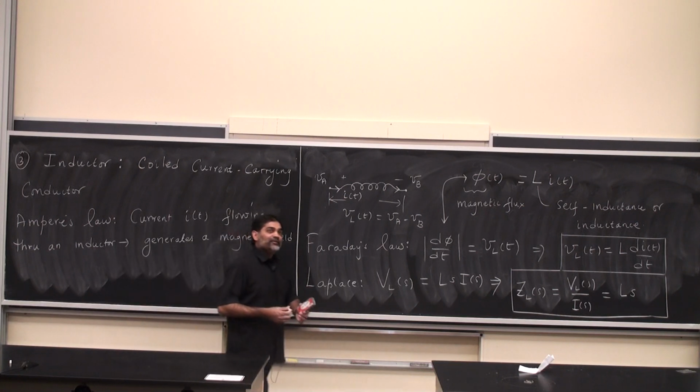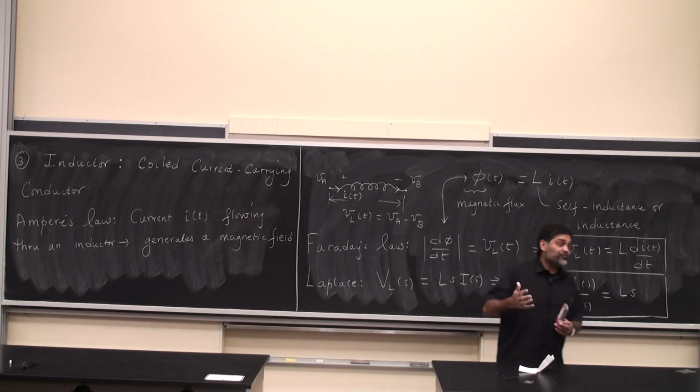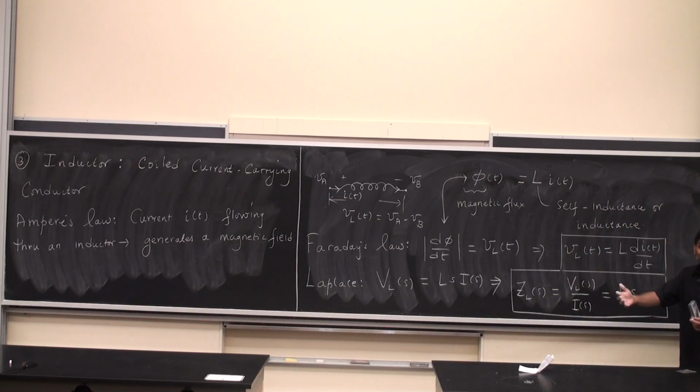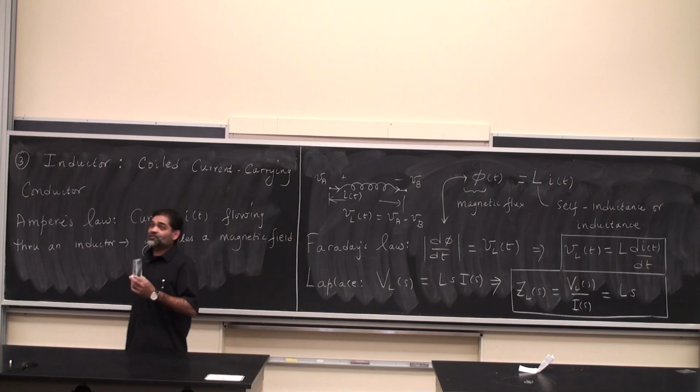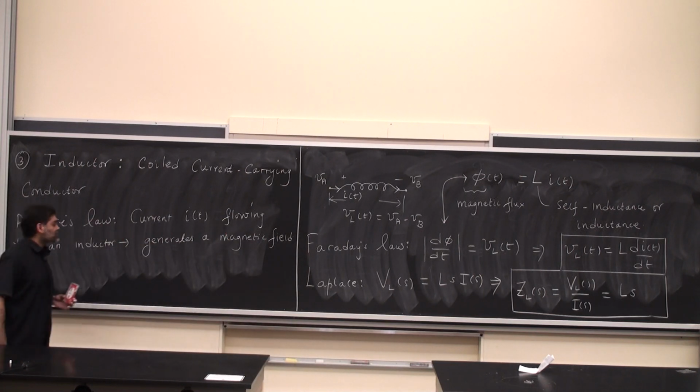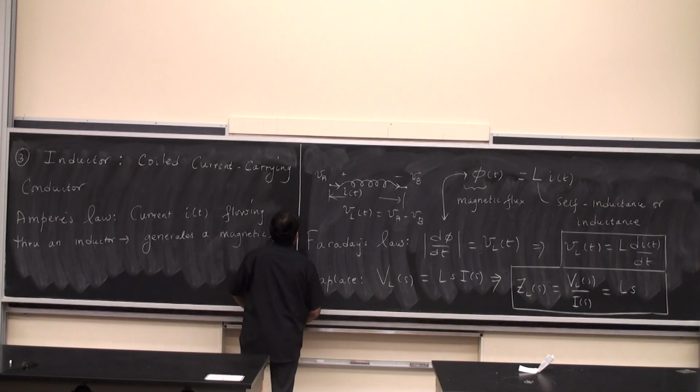Why are we using these impedance fellows? It's because we are going to go to the frequency domain. We are going to do that on Wednesday. Frequency domain is much more confusing than time domain, okay? And we want to take it step by step. And the impedance blocks are the best way to actually model things in the frequency domain, because you directly get the transfer function. Once you get the transfer function, you just do some substitutions and you call it a day.